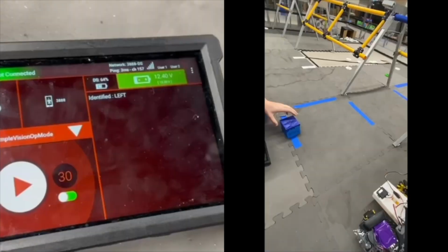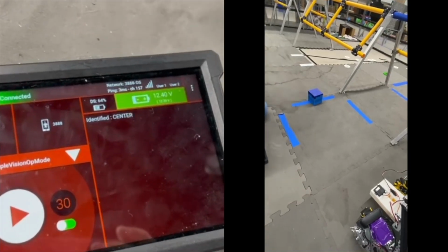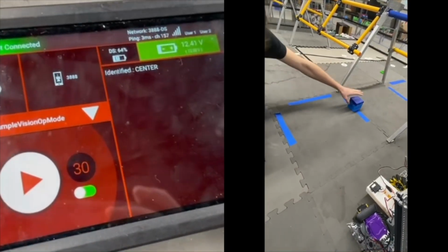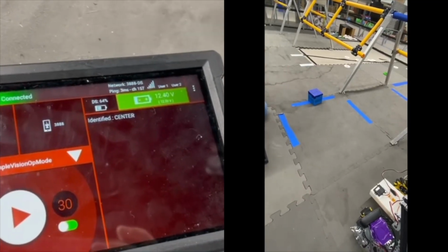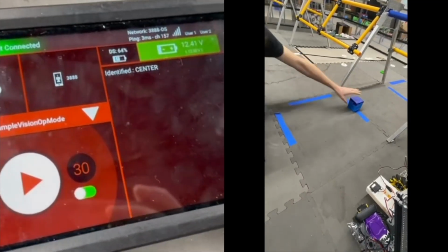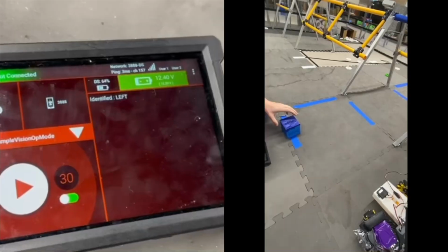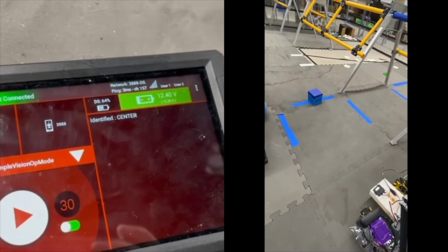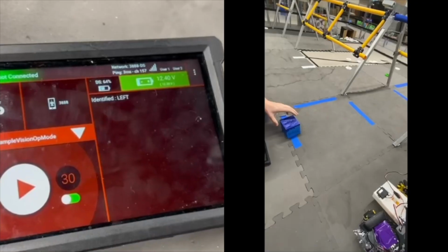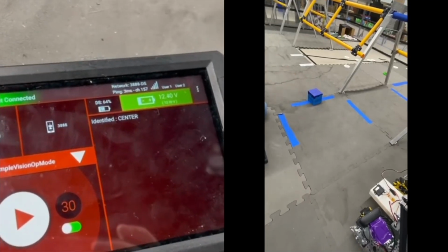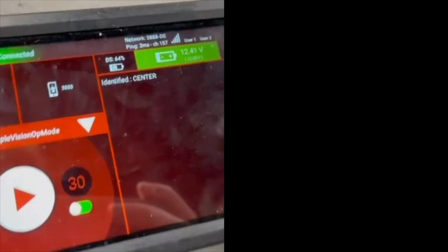Let's start off with the camera code. The camera code uses the vision processor interface with two rectangles, left rectangle and middle rectangle, having predetermined positions and dimensions. A hue saturation and value matrix, HSV, is employed using the singleton pattern to detect the starting position. The HSV is processed calculating the average saturation values, and the rectangle with the highest saturation becomes the chosen position. Rectangles are drawn on this camera stream for debugging.